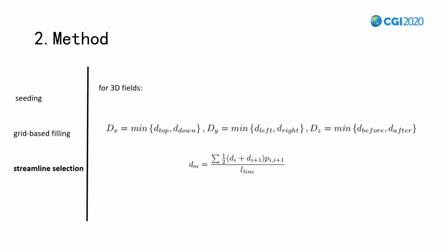This brings more selections for 3D fields. With the three parameters, the user can get more results according to the user's demands, which can help understand the flow field more conveniently. The thresholds of the three parameters are delta x, delta y, and delta z respectively. In addition, we could also provide the density control along an axis at an angle. It could be defined by users and could help users to limit the density in this direction.